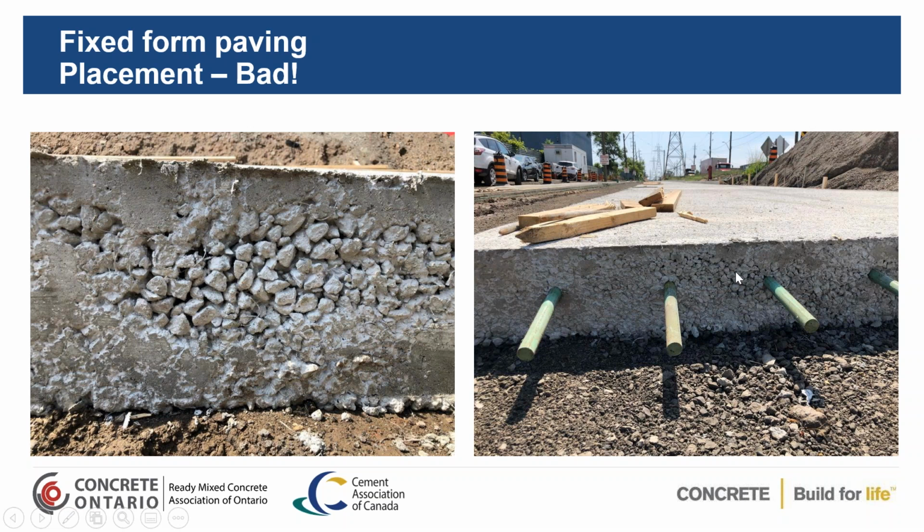Same thing here. We got an issue, especially around the dowels. There's a lack of consolidation around here. What's going to happen over time, with the loads, is these dowels are going to be moving and they're going to deteriorate the concrete around them because there's not a sufficient paste content here. And it's going to decrease the life of those dowels themselves. The pavement load will be decreased.